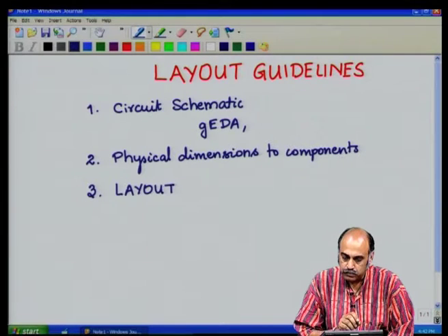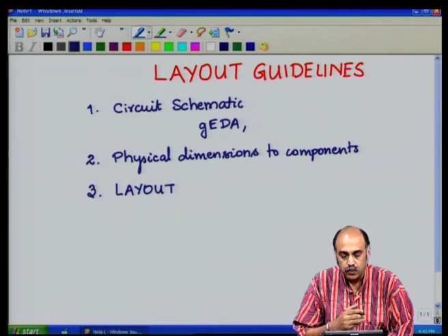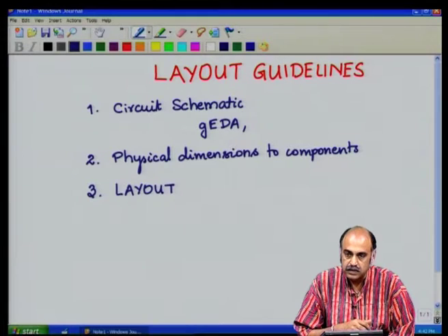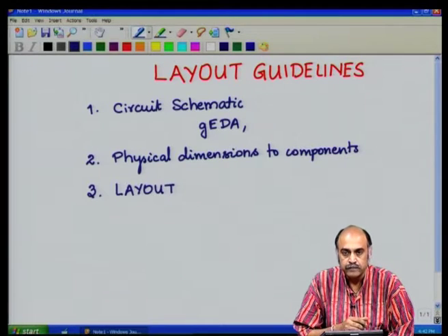Now, while we are at the layout, I should mention that the printed wiring board dimensions will actually come from the application. So, you should be pretty clear where this particular printed wiring board is going to be applied or where it will be ultimately mounted. Maybe it would be mounted in a 19-inch rack, or onto a custom enclosure, or it could be an extruded enclosure.